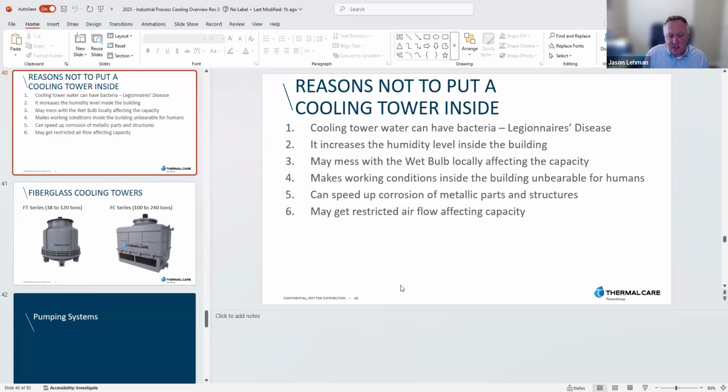But especially on the TurboCore chillers, you do want a larger buffer tank because you want the water flow going into the chiller to be more stable. The more stable that is, the more stable that will come out. We do have capacity control, hot gas bypass in a lot of our chillers that will react. But with any kind of PID control, what comes in affects what's going out, and so it's easier for the PID to react and create a stable temperature if what's coming in is stable.